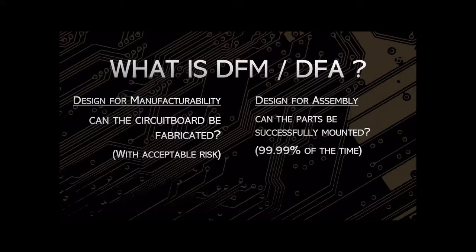Awesome, so let's get right into it. Today's big question, what is DFM and DFA? So DFM stands for Design for Manufacturability. And when we're talking about DFM, what we're focusing on is the actual design of the circuit board. Basically, we're running a form of spell check, which is able to answer the question, can the circuit board be fabricated with an acceptable level of risk?